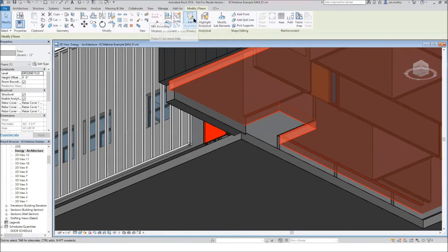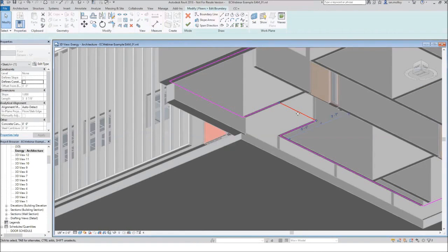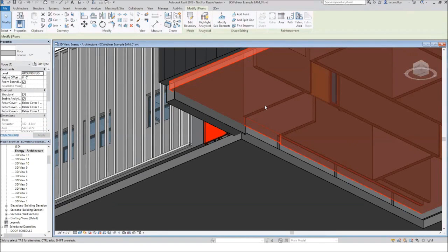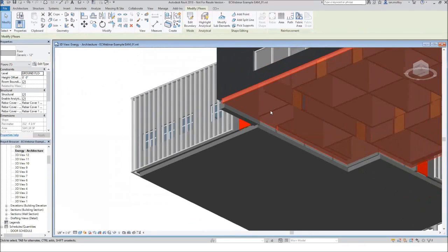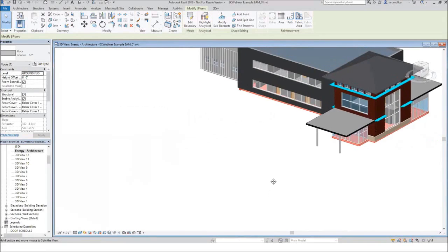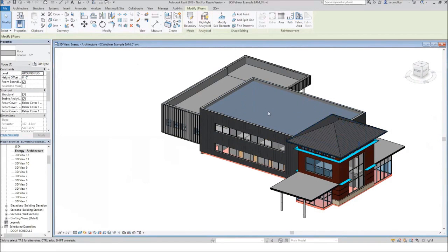So there's one of two ways I can deal with general gaps in the building. In this kind of case, it's really simple to just fix it, right? In other cases, I could maybe draw a patch in, or maybe keep it in a separate linked model if it wasn't something that I wanted in the main model. Or the other trick is you can use conceptual masking. Sometimes you've got models that have gaps all over them, like let's say an entire roof is missing and you don't know how to model the roof, or because of the way the thing is modeled, there are holes all over it. You can just extrude a conceptual mask sitting inside the building, basically capture the shell of the building, and that will shrink wrap the whole building, and you can analyze the model from there. So one way or the other, it's very, very quick to do.